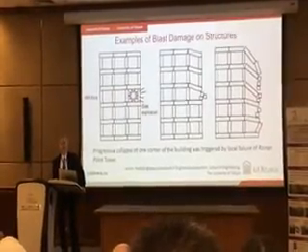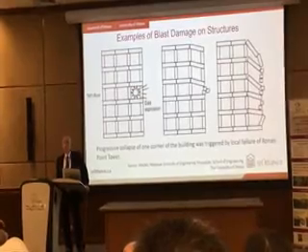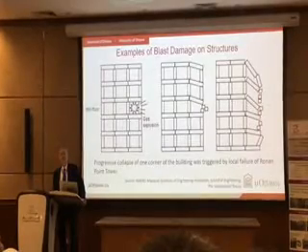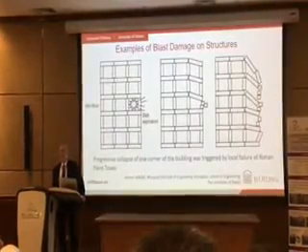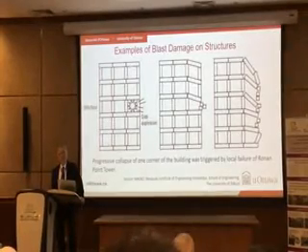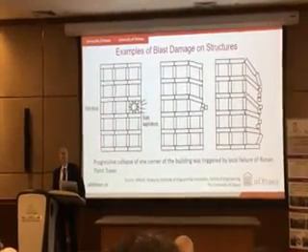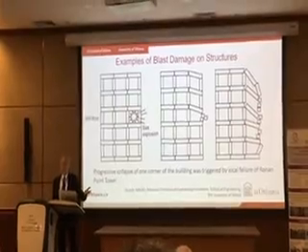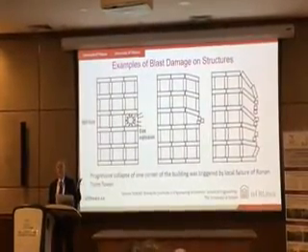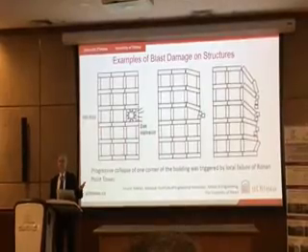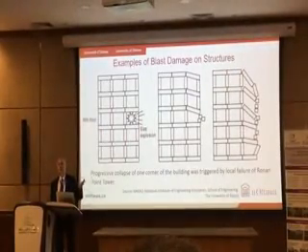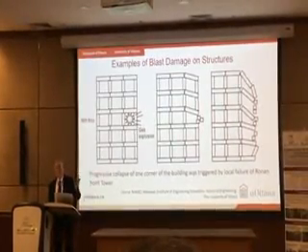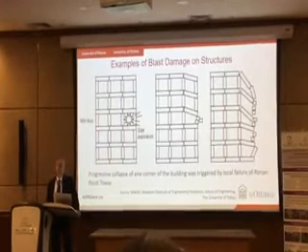As you know, progressive collapse is one member triggering partial or total collapse of a building. A good example is the 9/11 event. Right? In 9/11, an airplane collided with one of the floors, and that brought down the columns at that floor, and then the intense heat of the fuel reduced the capacity of steel columns, and then columns of that floor started failing, and the story below was not designed to carry 2 stories load, and then it failed, and the story below failed. So it was just a zipper effect. We ended up having progressive collapse.